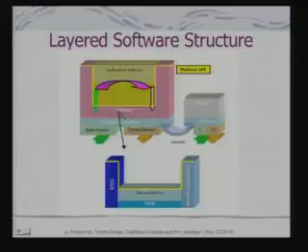and this software layer of the platform would consist of device drivers, that is, abstraction over the IOs, and the RTOS, that is, abstraction over the concurrency model, the model to support threads, processes, etc. And if you are looking at a distributed system, it should also have network communication support. Below that you have your architecture platform, that is your hardware platform, and this hardware platform would be interfacing with the input and output devices.